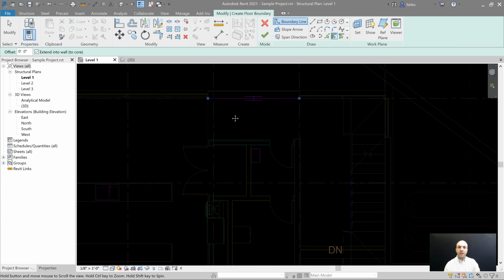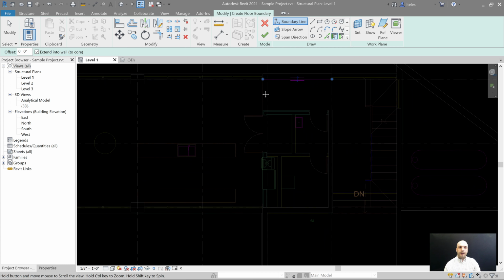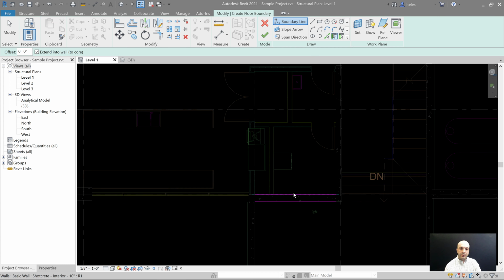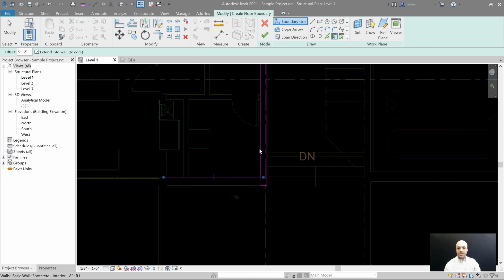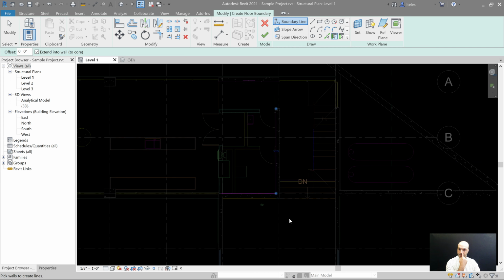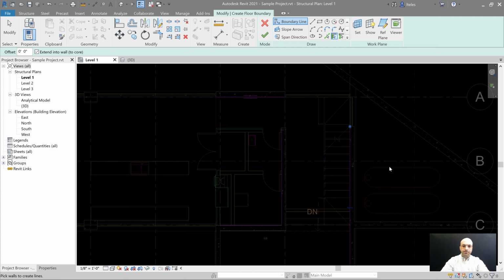All right. So now we've already picked our walls, and actually we can pick this one down here. We need to pick this wall right here, and we'll pick the inside face of that wall like that. So we've got those 3 interior walls chosen, but now let's choose this exterior wall right there. So we're telling Revit we want these edges to follow the wall if that wall moves.